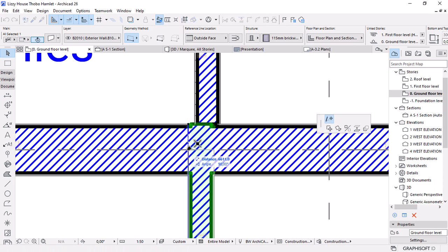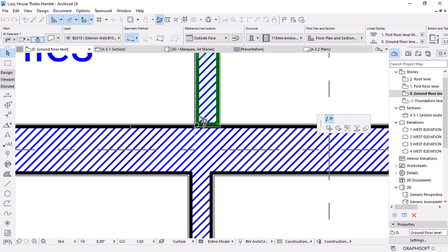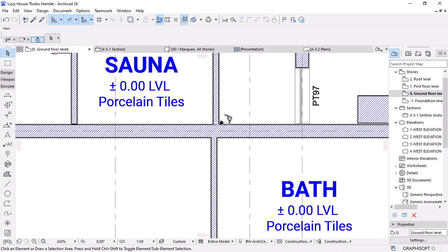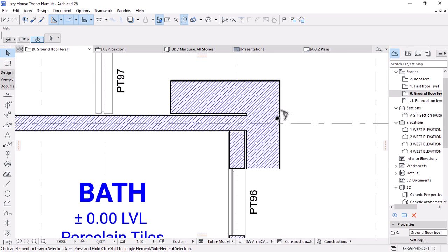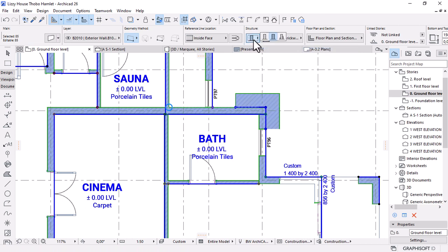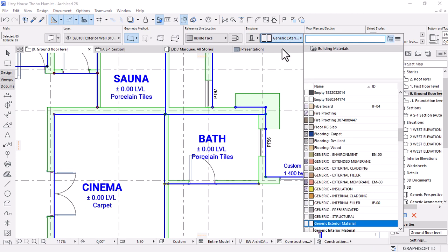I'm going to use, how can I say this, a different type of wall display. It's going to be all solid without having any finish. That will help me to speed up the process. So what I'll do, I'll select all the walls, and then I'll remove the composite and use the basic. On this basic, let's find a brick.